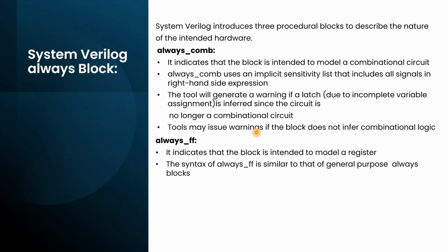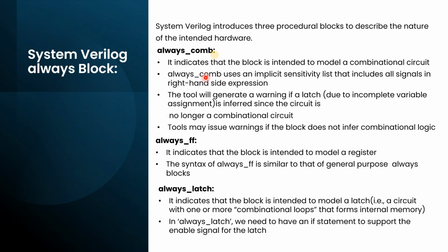So in SystemVerilog, there are three always procedural blocks differentiated with different keywords. always_comb to implement the combinational logic, always_ff to realize the flip-flops or the registers or the sequential elements, and always_latch to implement a latch. So what happens if we use always_latch, but